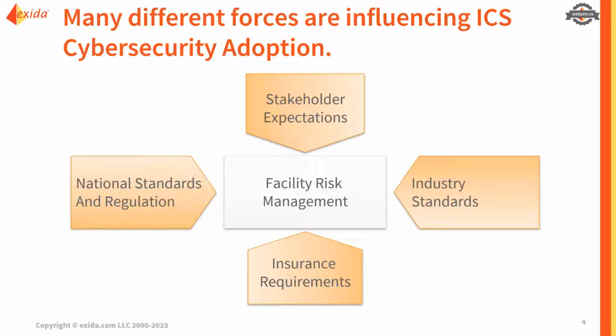In addition to the cybersecurity standards, it's also important to realize that cybersecurity is being highlighted in safety standards as well. So the 2016 release of the IEC 61511 standard included specific requirements around doing cybersecurity risk assessments for the SIS and connected systems. So if a manufacturer is providing a configurable component that's going to be used in a 61511 safety system, or people who are providing, let's say, a certified system or a certified site that includes a number of safety functions, there are now specific requirements to doing a cybersecurity risk assessment as part of that.